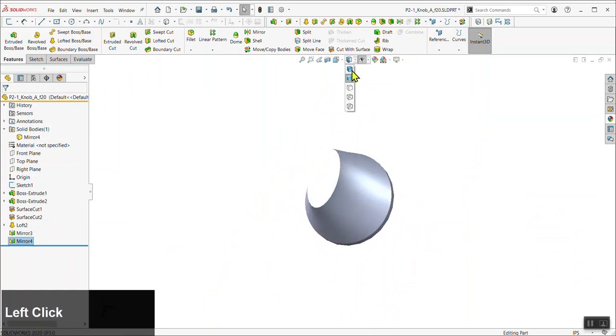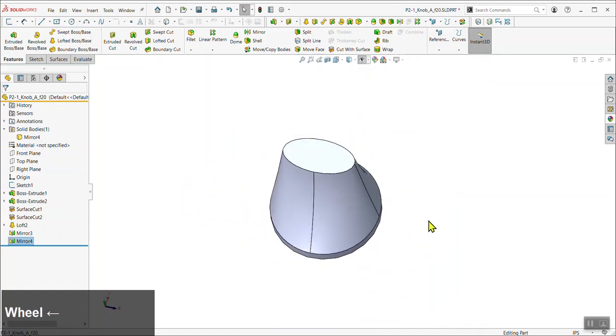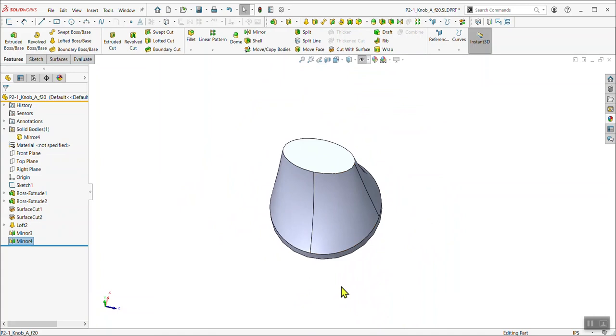So just be aware of seams that are caused by lofts, and be aware that sometimes going left to right is better than top down. And that is the main takeaway from this demo, aside from learning lofts.